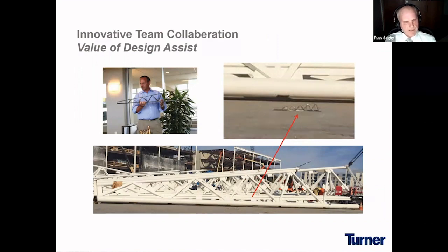And the steel erectors had to figure out how to pick them up, turn them over because they're laying upside down in the parking lot, and get them into place in a safe manner. And the way they did that was to build this model that the project manager is holding. And with his team of workers, they figured out how to strap it, how to rig it, how to lift it safely, and not lifting over anybody's head. Safety is the number 1 priority, and quality is number 2 priority.